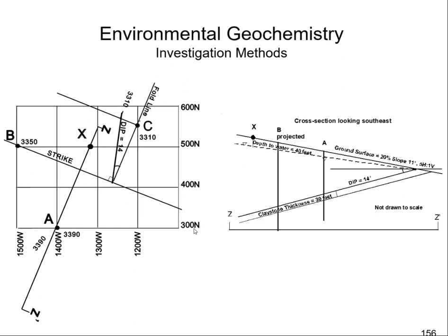And in this particular case, it is true for the northerly numbers. They are increasing from an east-west baseline down here somewhere. But the westerly numbers are increasing to the west. If we had a standard XY with 0 located at the intersection, then these would be increasing to the left of that y-axis as opposed to the right. A lot of people will confuse these and not really think about what that W means. That means westerly, which means that it is increasing to the west of some north-south baseline over here.